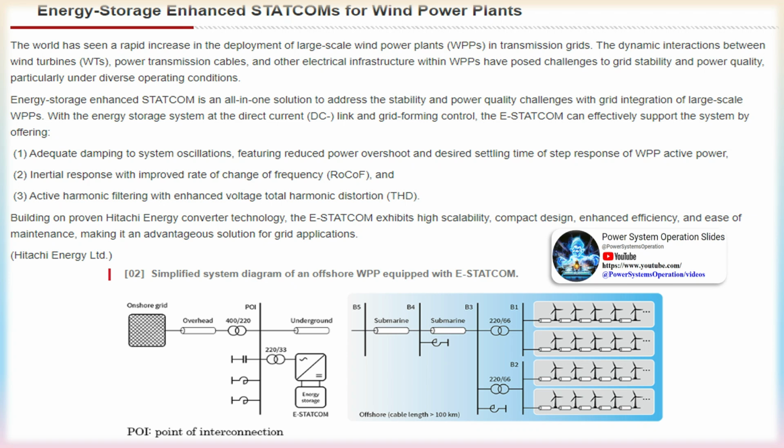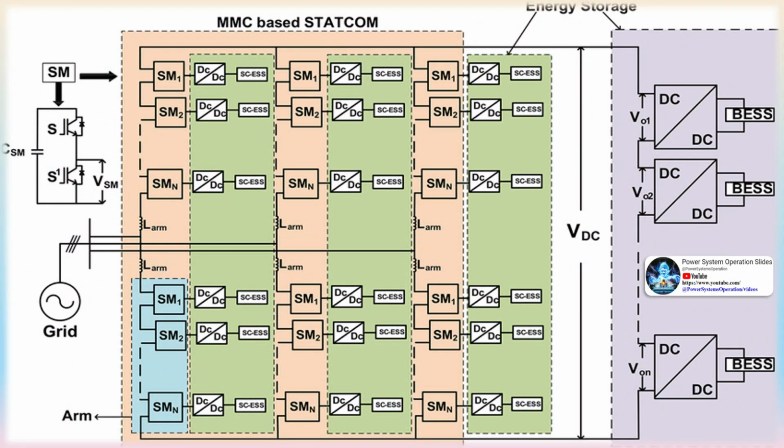Additionally, this solution enhances control over power flow at the PCC by adjusting the direction of power injection, whether upwards or downwards. Without energy storage, FACTS devices have limited flexibility and sustained effectiveness in supporting the power grid. Integrating an energy storage system (ESS) with FACTS devices allows for independent real and reactive power absorption or injection into the grid. This integration results in a more economical and flexible power transmission controller. When a transmission line experiences intermittent power transfer variations, a FACTS plus BESS combination can be used to regulate and adjust the power flow within the loaded transmission line. The superior performance of the combined FACTS plus ESS system is likely to be more appealing to transmission service providers.